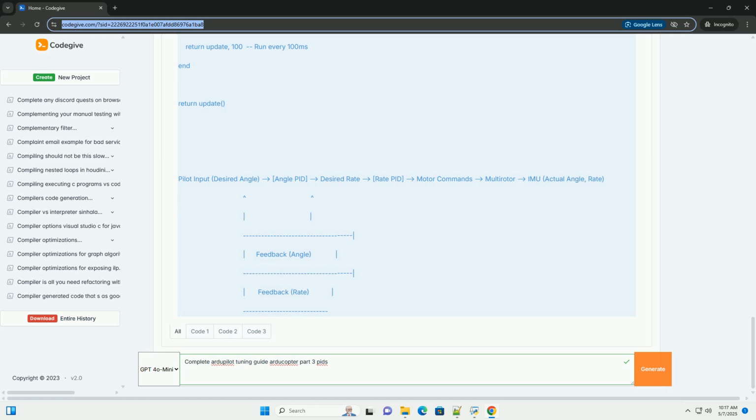3. D gain tuning. Increase D. Increment ATC_RAT_RLL_D or ATC_RAT_PIT_D in small steps. Damping helps to smooth out the response and reduce overshoot. It can also help to eliminate very fast, high-frequency oscillations that P gain alone can't handle.